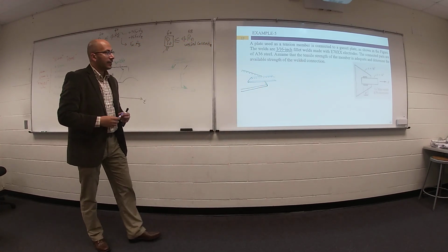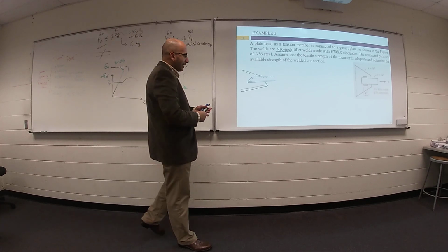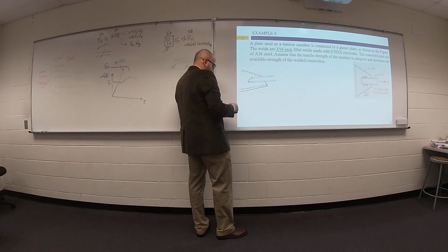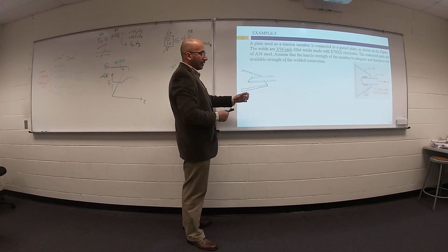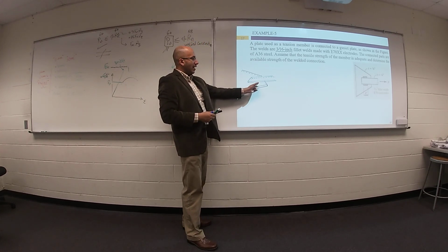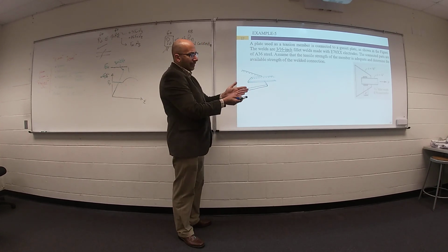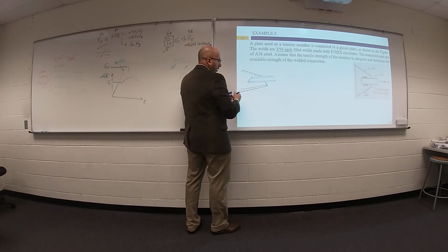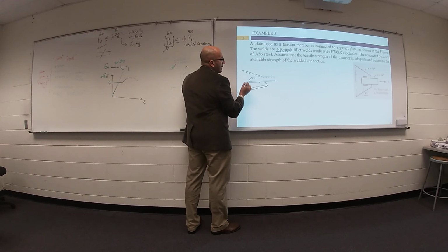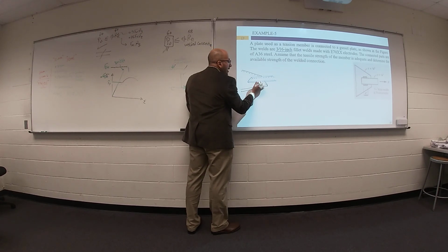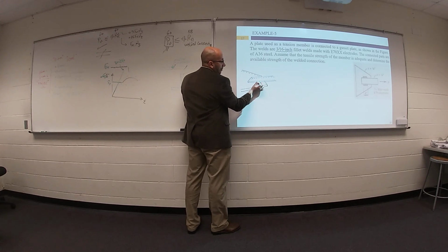Okay? Between this member and this member, at this location we have right angle. Between this edge and this surface we have right angle. So 3/16, 3/16 I will do weld. You can imagine?